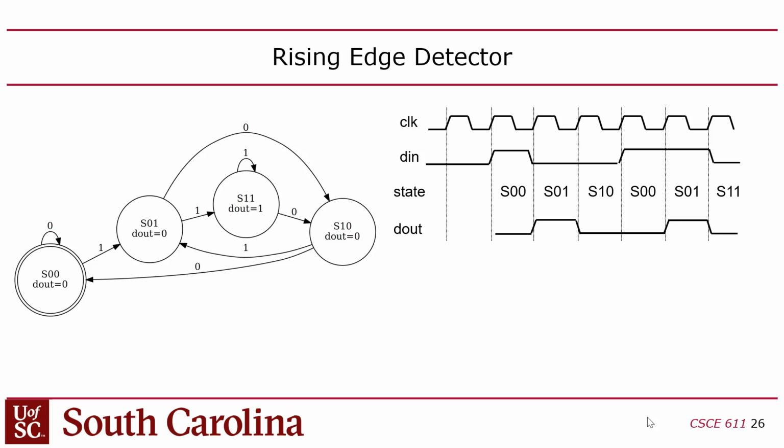So if I'm in 0, 1, I would have had a 1 and a 0. That would have been my rising edge. So probably I should have had a 1 here, actually, right? I think what happened is I got the output wrong. So that should be D out equals 1 there, and these other 3 should be 0, right?